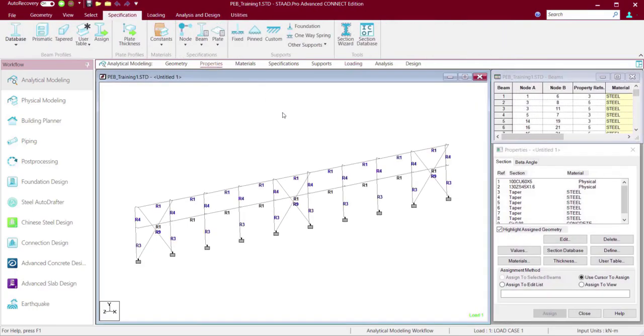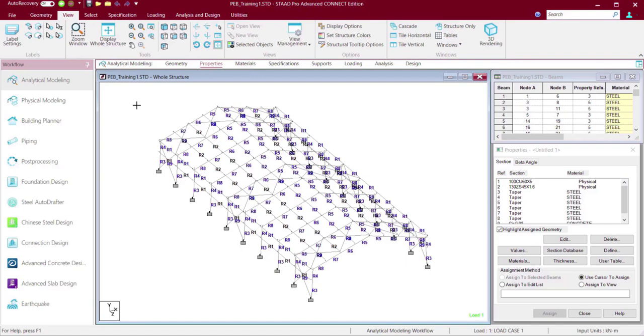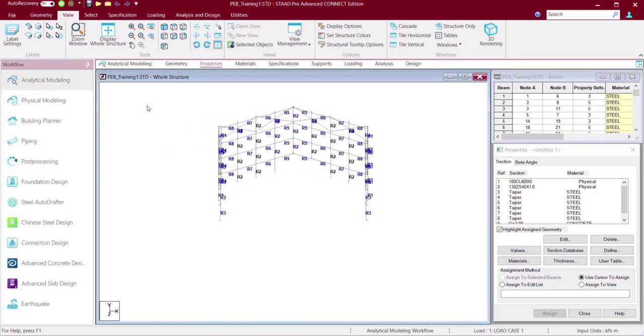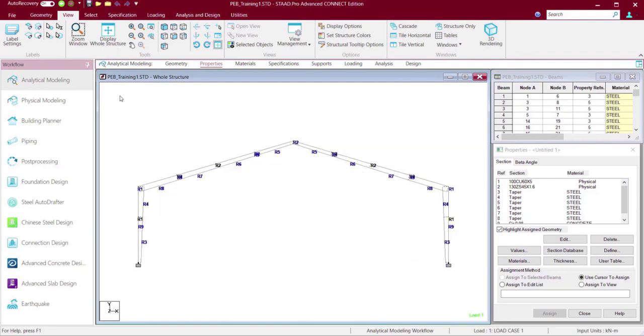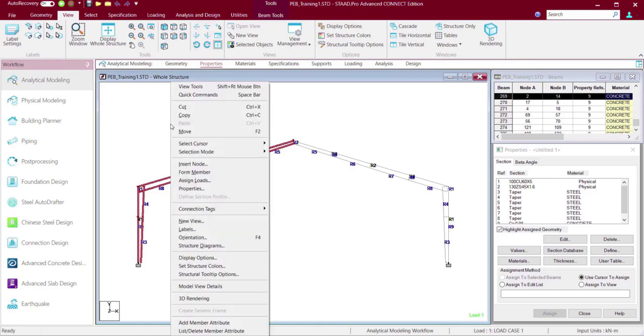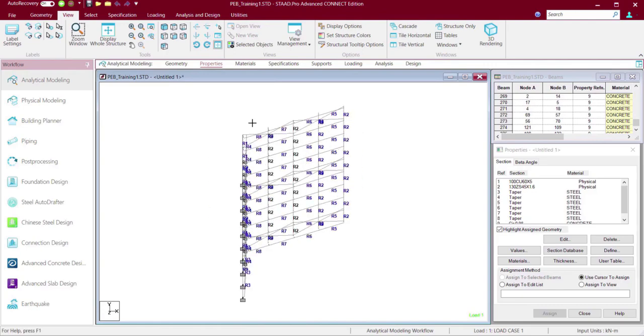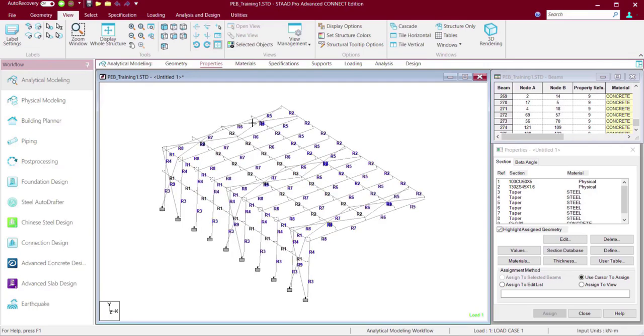Now for this phase, it's over. Now we need to take the slope portion because wind load is also supposed to hit on the building slope. So we are first selecting one half of the building or one part of these two slopes. So we are removing this cross bracing from the selection.